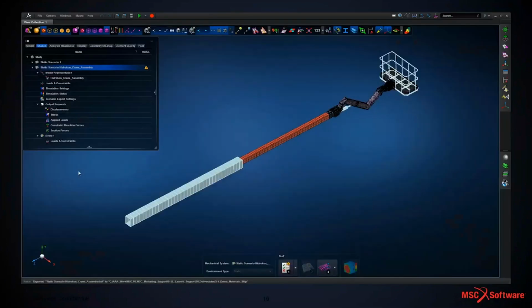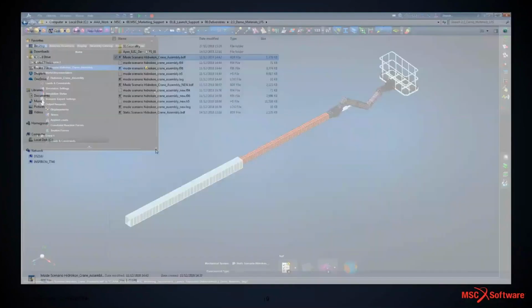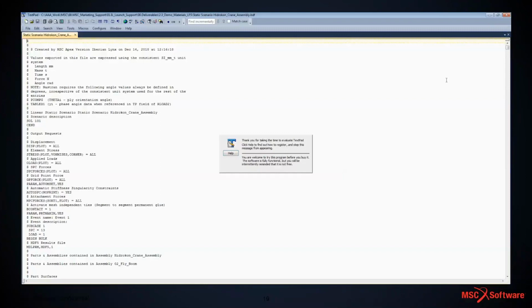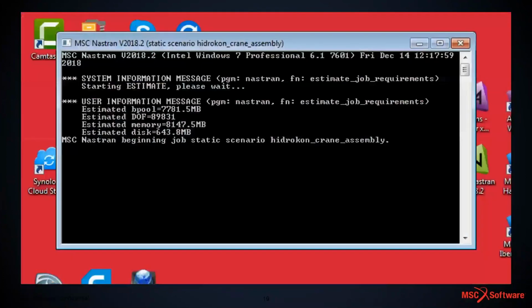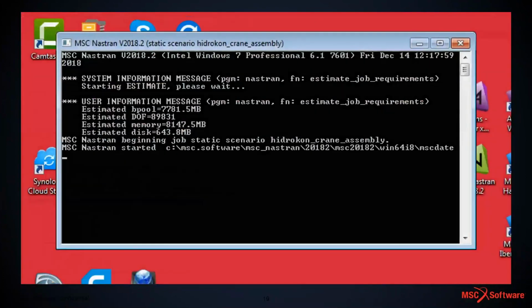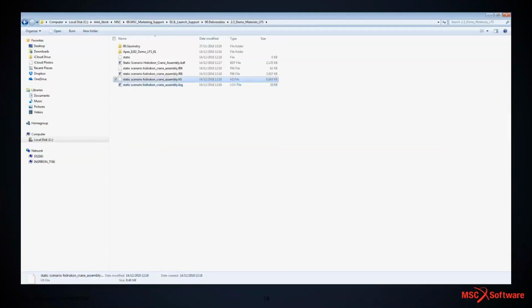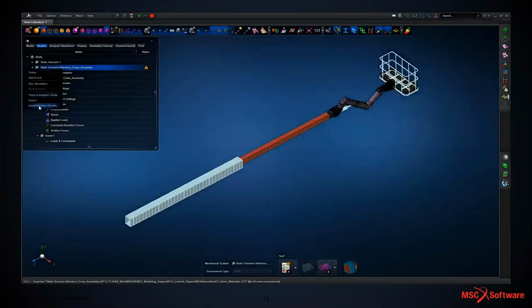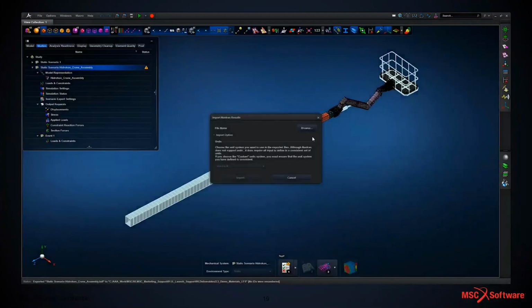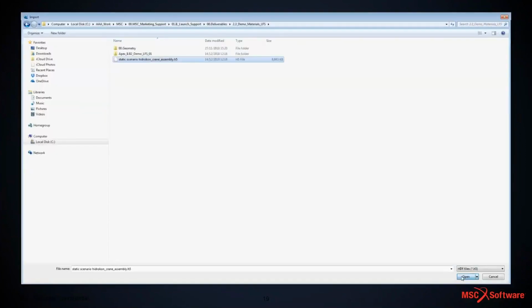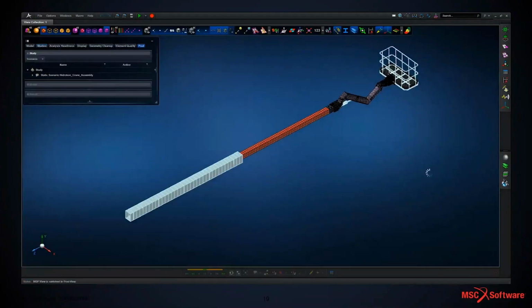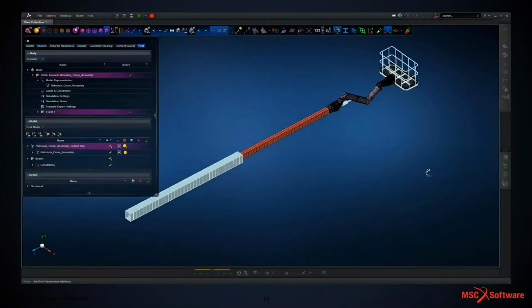So looking at this gantry type structure, we've got the Nastran deck written out. You can just double check the deck for the output request, that type of thing. We can run Nastran externally and then develop the Nastran HDF5 result format. We can read that by importing those results back into the Apex environment, and then we've got full post-processing or result exploration capability within Apex.